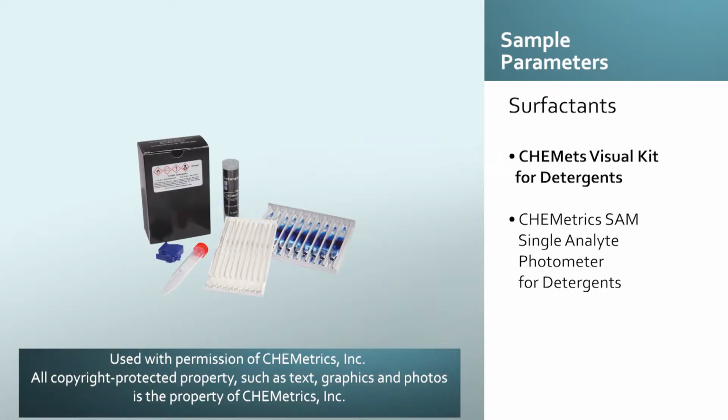Surfactants. The EPA New England Bacterial Source Tracking Protocol lists the MBAS test kit, for example, Chemetrix K9400, generally referred to as Comet's Visual Kit for Detergents, Anionic Surfactants, MBAS, as example instrumentation for surfactant sampling. This method involves snapping the tip of an ampule filled with reagent into a sample cup filled with a sample to be tested. The vacuum in the ampule will pull in the proper volume of sample when the tip is snapped.